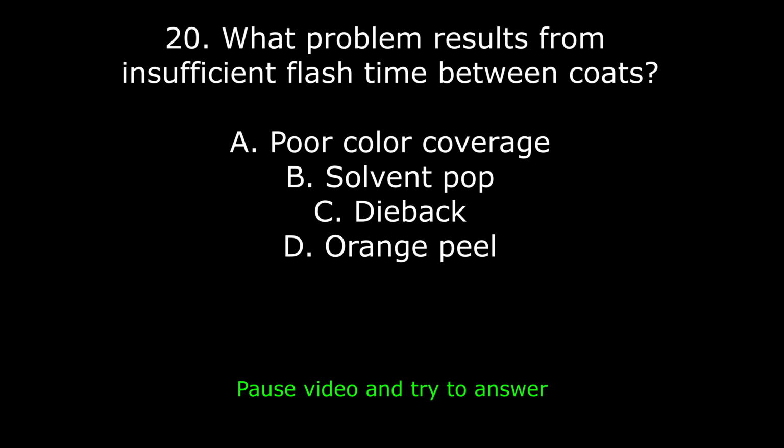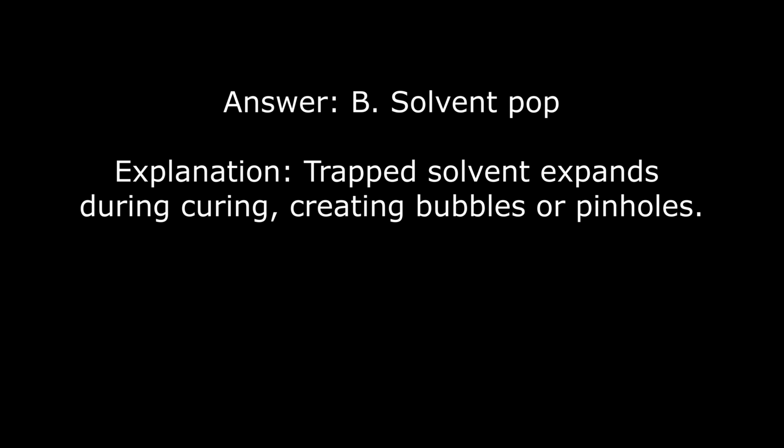Number 20. What problem results from insufficient flash time between coats? A. Poor color coverage. B. Solvent pop. C. Dieback. Or D. Orange peel. The answer is B. Solvent pop. Explanation. Trapped solvent expands during curing, creating bubbles or pinholes.